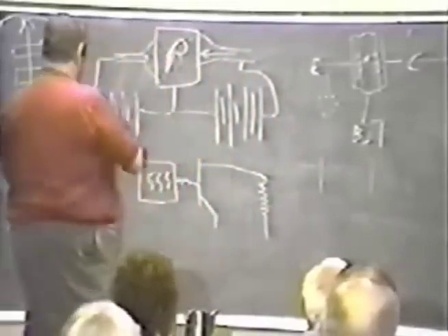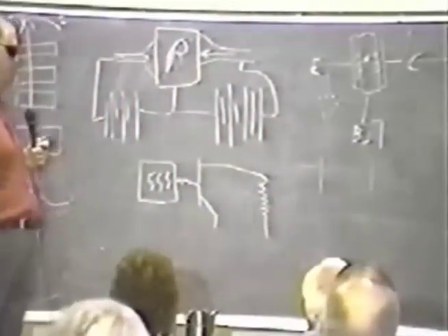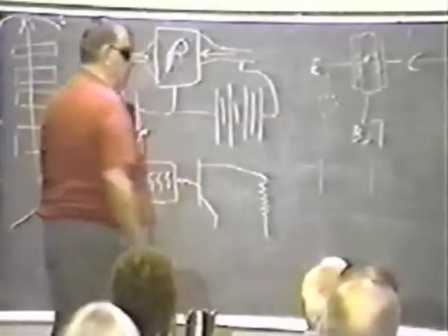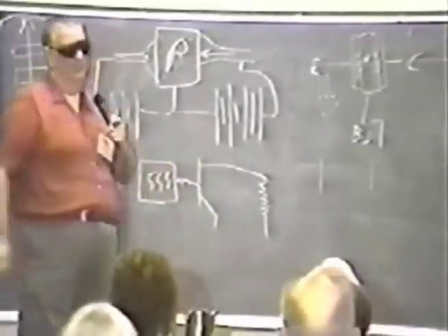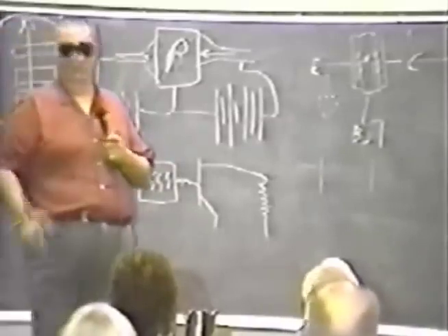The whole impedance of this thing is about 1,000 ohms. The current through the transistor is maybe about 10 milliamps. The whole thing draws about 15 milliamps from a 9-volt transistor radio battery.